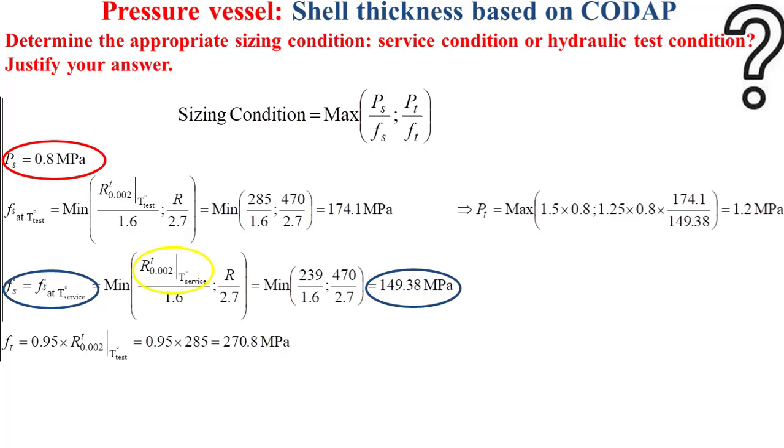It's to note here that the yield strength at the service temperature, which is 170 degrees Celsius, as I stated in the previous video, is calculated and its value is equal to 239 megapascal.